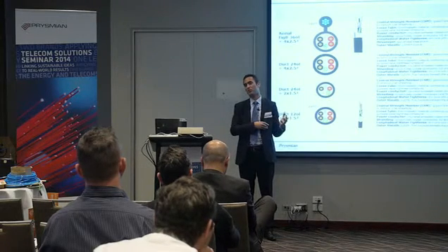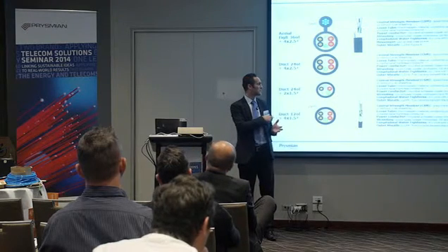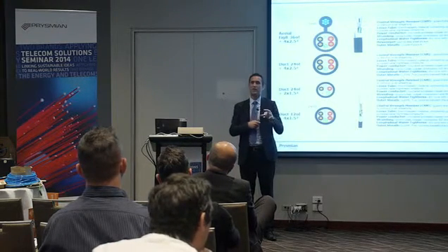Of course, at this moment, we are talking 100 meg. Those are, I mean, the hybrid fiber coax can do it when you bring fiber to the last amplifier. Fiber, we are talking now 1 gig Ethernet, 1 gigabit per second at the end user. Only fiber will be able to do that. Maybe a bit of G.fast in the VDSL world, but G.fast needs to be 70 meters maximum.